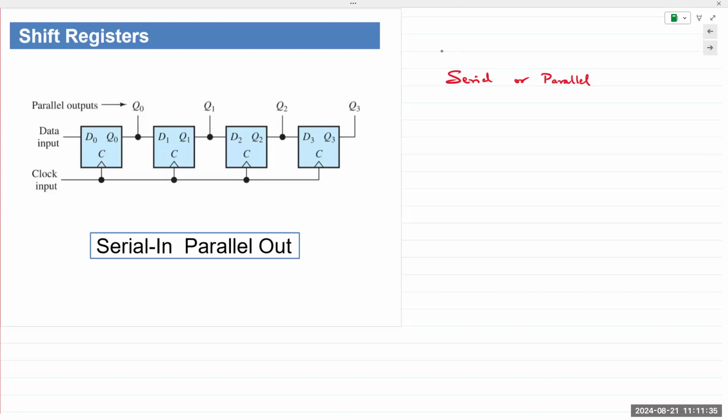USB. The name stands for Universal Serial Bus. So a USB port has 4 pins. It has a plus and minus 5-volt line, and there are two other lines for data, D plus and D minus. So if you use a USB charger, it only has 2 outputs, does not have anything for data, just has a plus and minus 5-volt line.